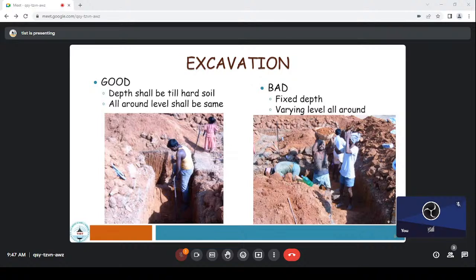Normally, we will cut the soil for the foundation, and we have a tendency to store it on top of the same soil, adjacent to it. Immediately when you do such an activity, you can see how clumsy it is. On the back side, you can see how clumsy it is. All the soil is excavated and kept on the top of the shore. There are 100% chances of this sliding down. Am I correct or not?